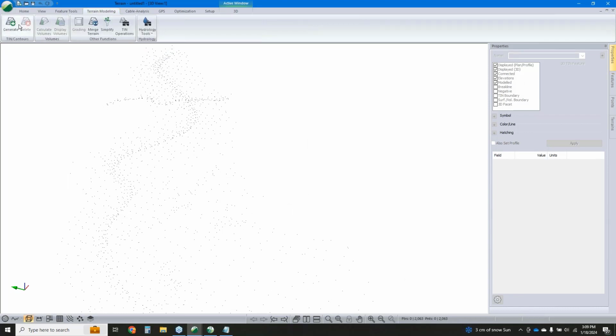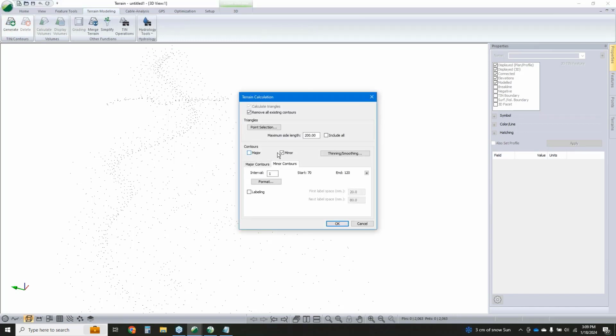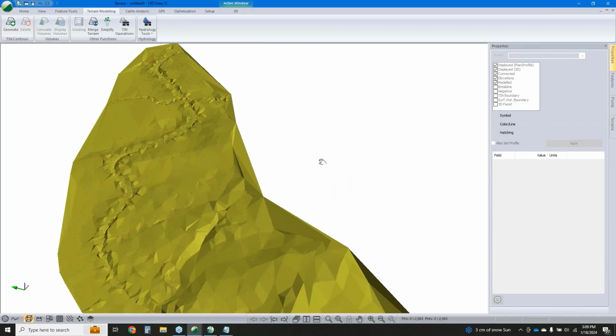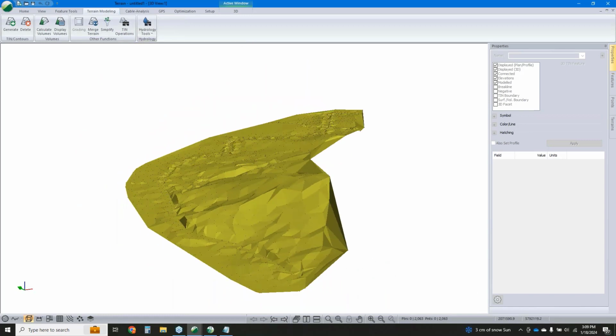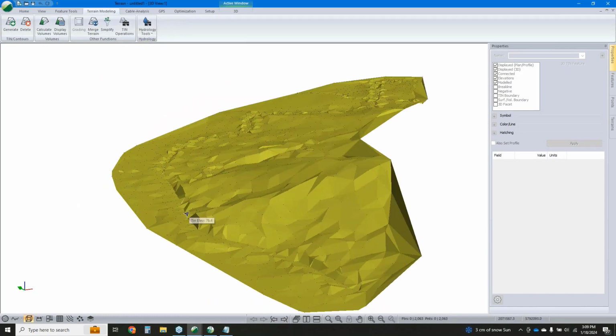And if we were to model this right off the bat, we'll talk about this more later, but if we just use those points as points without formatting, well, it's not the nicest surface. And breaklines will be a really important tool to help us eliminate these triangles and force triangles where we'd like them. So I don't want that triangle there, but I probably would like a triangle from here to there. We'll talk about that with breaklines.